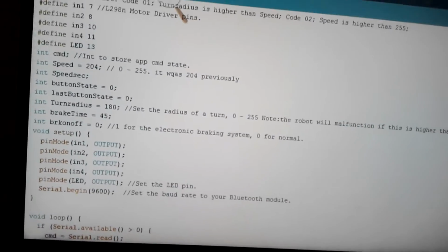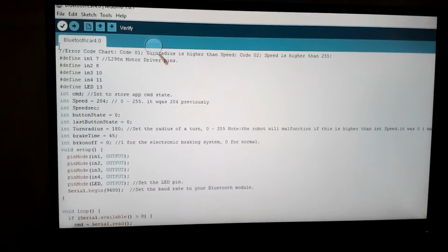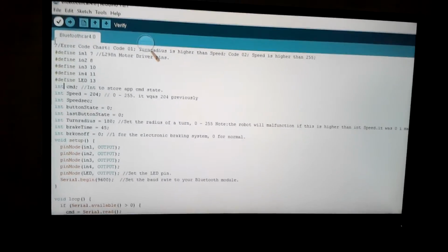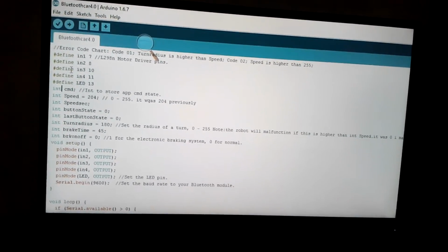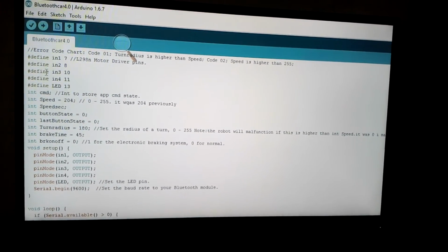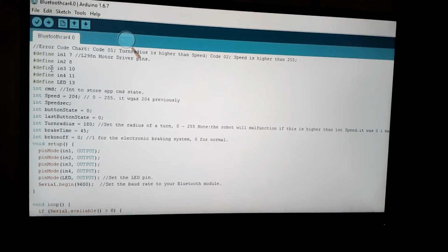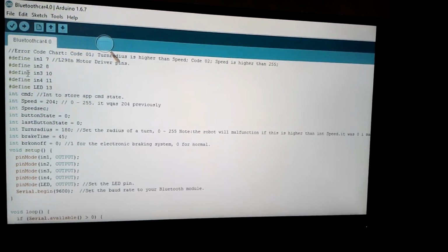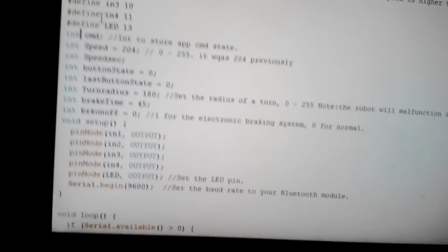Okay, we have used an Arduino Uno as mentioned before. For any Arduino microcontroller used, we need to program it. For programming an Arduino, we have a particular IDE, which is the Arduino IDE. We have written our code here, and then we have compiled it on this PC, and then it was transferred to Arduino via USB cable. There is one point to note that Arduino uses serial connection to transfer code, but the serial connection is done over USB. Okay, let's get into the code.